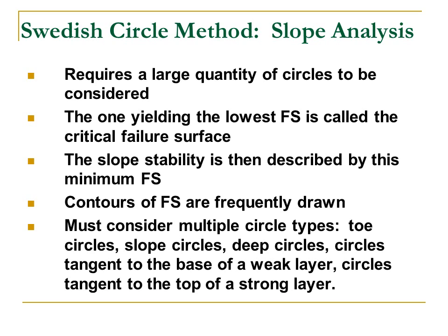There are a number of issues related to slope analysis with the Swedish circle method. It typically involves a large number of circles to be considered. The circle that happens to yield the lowest factor of safety is called the critical failure surface. The slope stability is then described by that minimum factor of safety, and we often associate the factor of safety with the